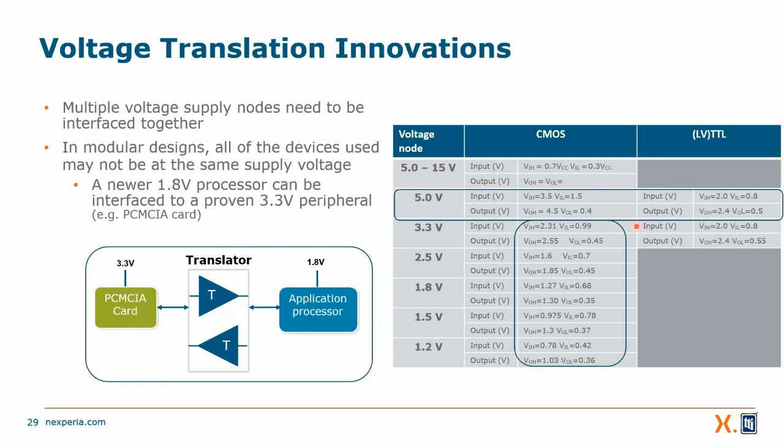So there are a wide variety of different devices available for it. Because the different voltages are out there, there is the HEF family from 5 to 15 volts all the way down to these 1.2 volt devices. At each one of those, the actual voltage for an on bit, a high, and a low bit are different voltages, and I need to compensate with a translator to convert the voltage from one family to the voltage of another. That is why we have this plethora of devices out there now, because we need to convert so many voltages from one family into another.